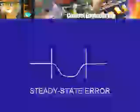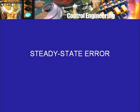Now, to repeat, it is in connection with steady state error, and with words and expressions such as error driven or error operated system, that one may get a wrong idea of what is going on. Our very primitive drive, where EA was kept constant and field current was kept constant, suffered from this defect, that there would be steady state error. If the load torque changed, the speed would change, maybe by 1%, but it would change and remain at the changed value. If accidentally the supply voltage changed, the speed would change and remain at the new value. So, that drive had steady state error.